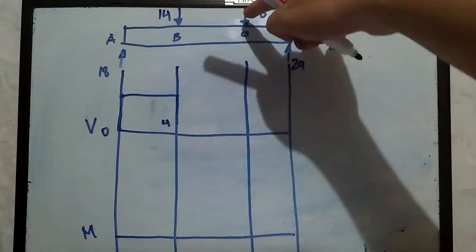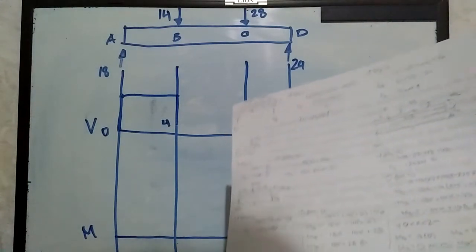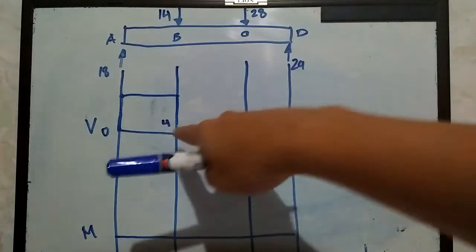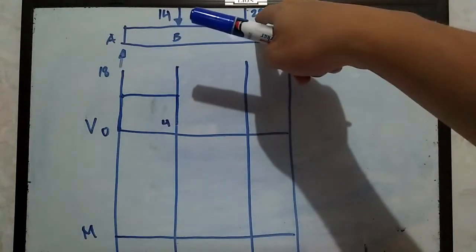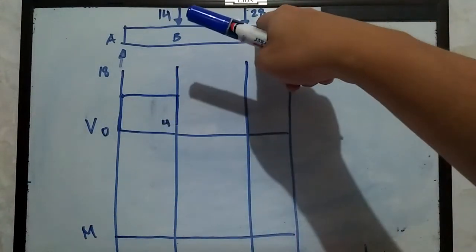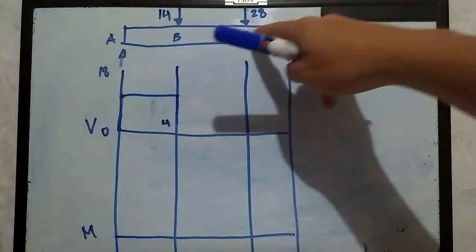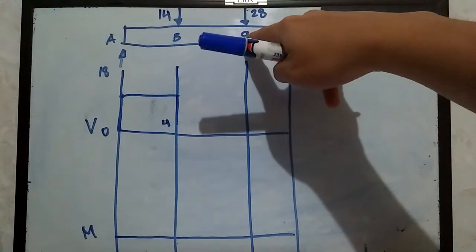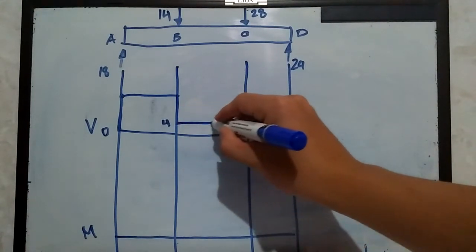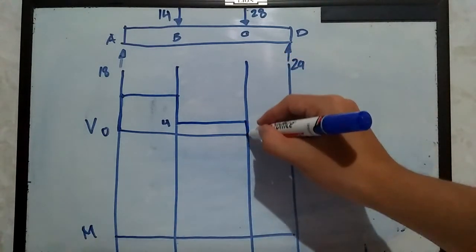And then let's move on all the way to C, which has a shear force equivalent to negative 24, because from 4, we need to minus it by 28. So 4 minus 28 is negative 24. And the shear force that we managed to solve at section C is negative 24. So it's correct. So let's move on to C. Then it went down to negative 24.